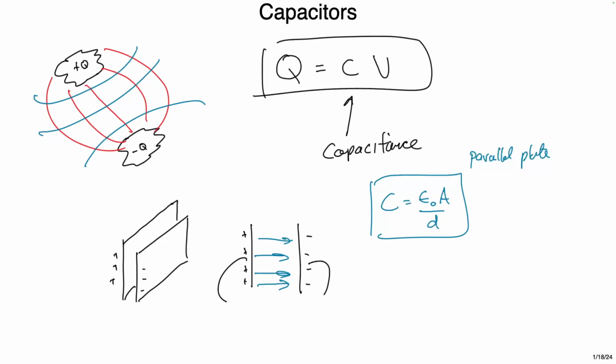So how do we get more capacity? How do we get more capacitance on our capacitor? Increase what? Area. We can make the amount of material bigger, right? That D right there is the separation distance between the plates. And so what does that tell you about storing charge? What happens as the distance between the plates gets smaller? Note that it's in the denominator. It increases the capacity for the capacitor to store charge.